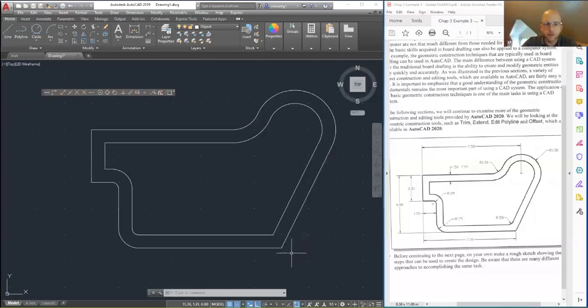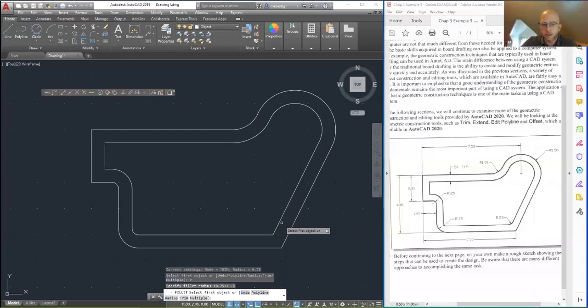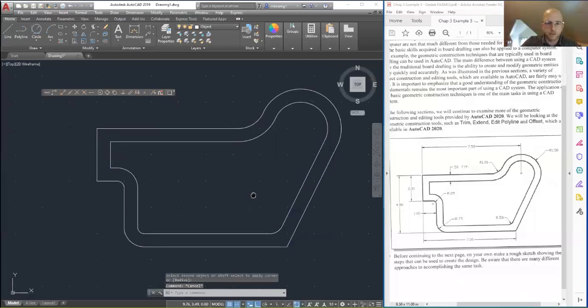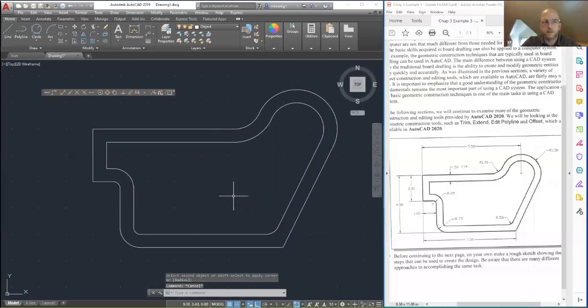Okay, down in the lower right corner, we didn't have a fillet, so that's just a hard corner there. Let's say we want to fillet it just on the inside. We can do that by just using the fillet tool and specifying the radius. I'll type R for radius, and this one's going to be 0.5. And then I just select these two objects, doesn't matter which order, and that'll give me a 1/2 inch radius fillet there. Okay, so now we're ready to take a look at some other tools before we dimension these.